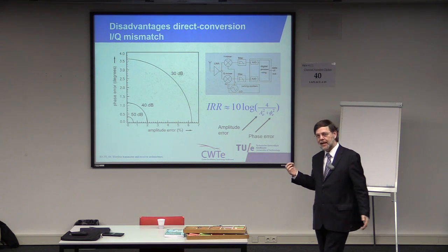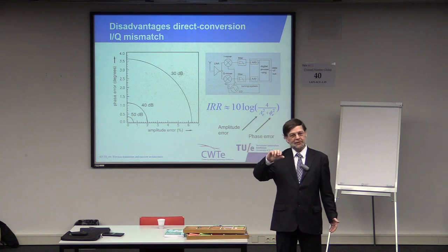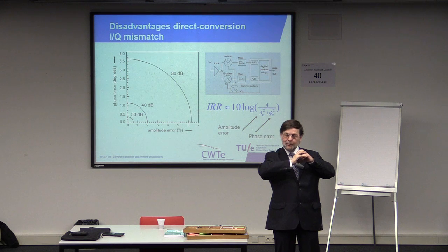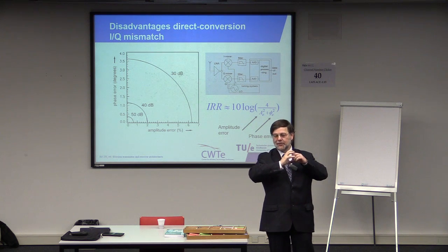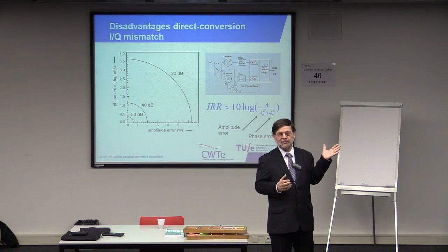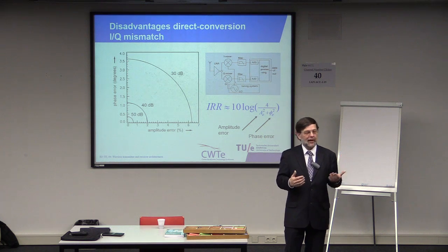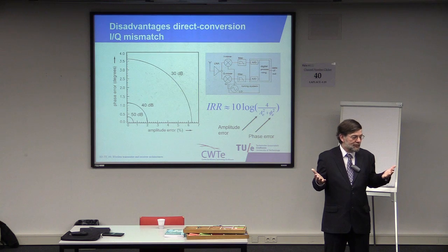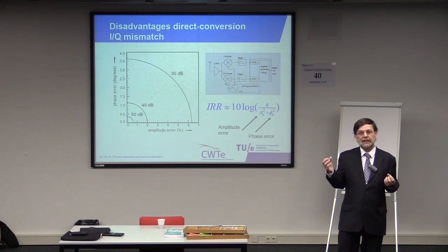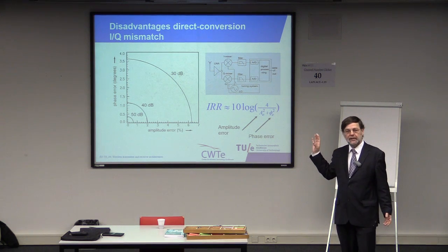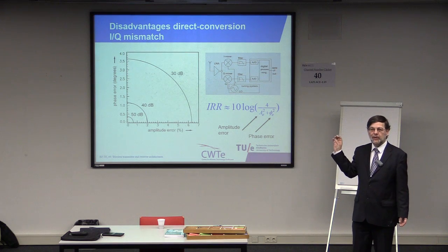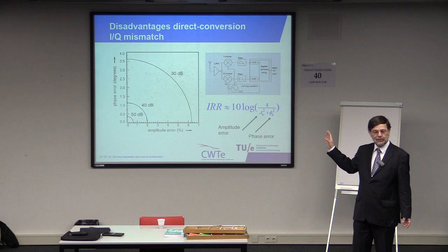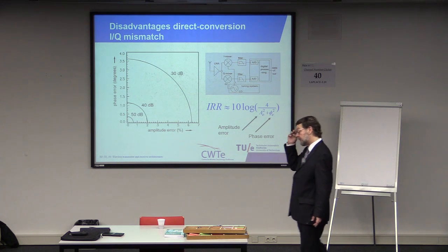For that reason, in the lab, we use special torque keys to reproducibly connect connectors always with the same force, and so always with the same length. Even so, 60 micrometers is very, very small. And if you go to higher frequencies, this number gets smaller. Obviously, it scales with frequency. And that means that for 0 IF, there's almost no choice. You will have to build in some calibration to fix this, because you cannot, by design, achieve this level of accuracy.